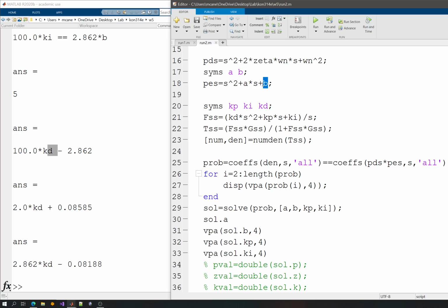So my residue poles are still at minus 2.5, and that's a fact. Now, if I increase B, the oscillation of those poles will increase, which means that the zeta value will decrease. So this needs a little bit of experience in controller design.